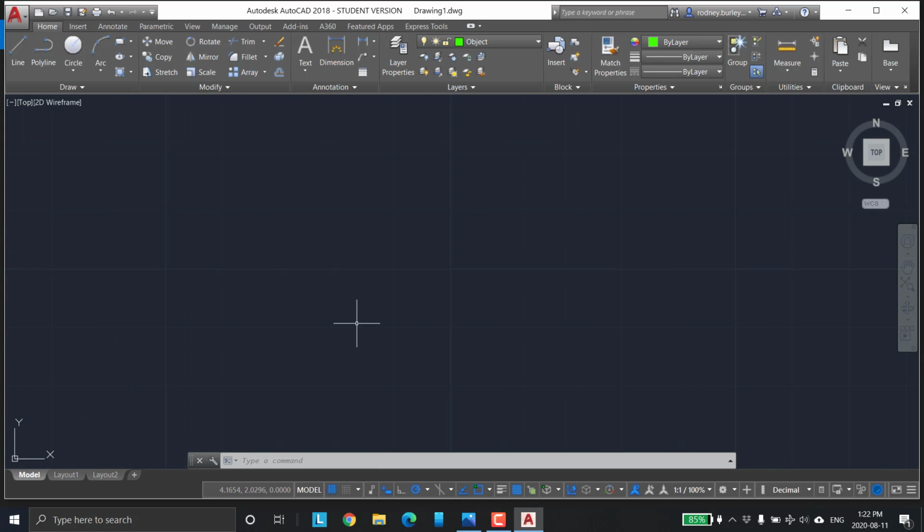Right now, if I zoom in, you'll see these boxes. It's not grabbing those boxes. So just for a second, I want to click a line. Click that little guy right there, and it'll allow me now to draw. When I click the line tool, it will jump onto a line. I just want to start on one of those boxes right there. Once it's locked, don't click anywhere else, just come down and click that off.